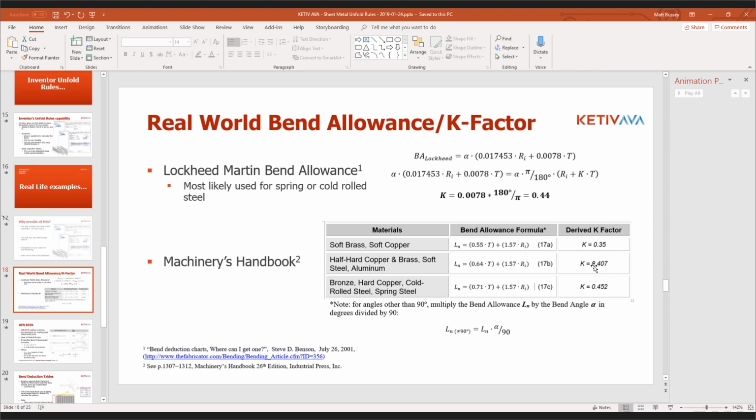For aluminum, however many different kinds of aluminum there are, that many different K factors are in some of those books. Yeah, I believe so. But I tend to go to things like Machinery's Handbook first. Start there and then work my way out. Exactly. And then if you're not getting what's expected on your machinery, then maybe do some tests, because I know that all machinery is a little bit different.